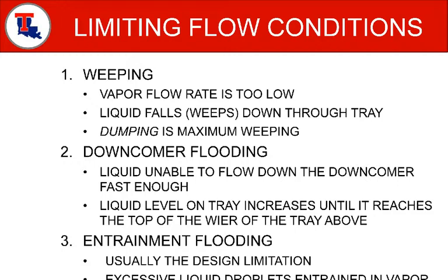This is usually the design limitation. Remember in absorption, it was the gas velocity. In distillation, it's the vapor velocity. It's usually the entrainment flooding. That's the design limitation, so we'll base all our calculations on this. You see the different scenarios that are caused by excessive gas velocity, low gas velocity.